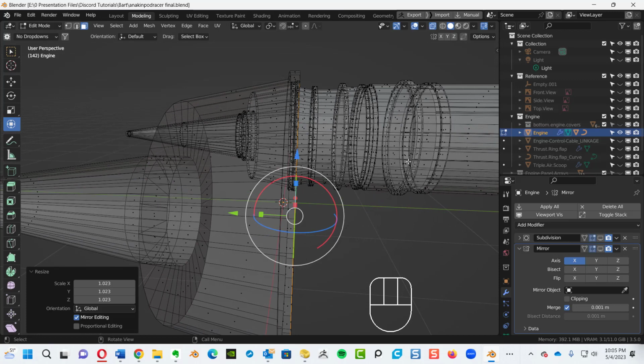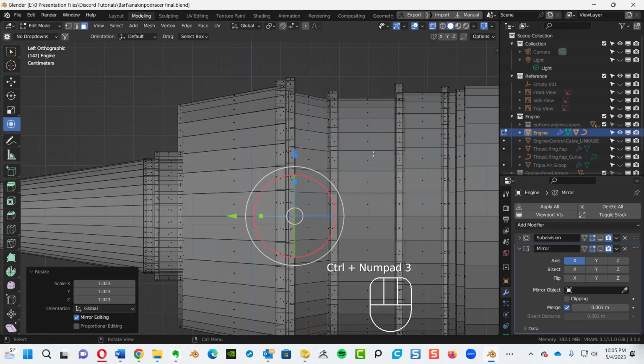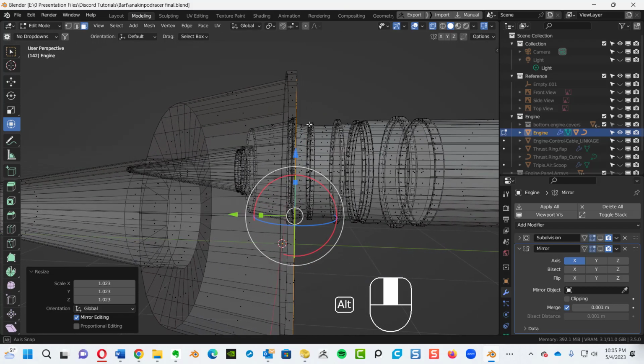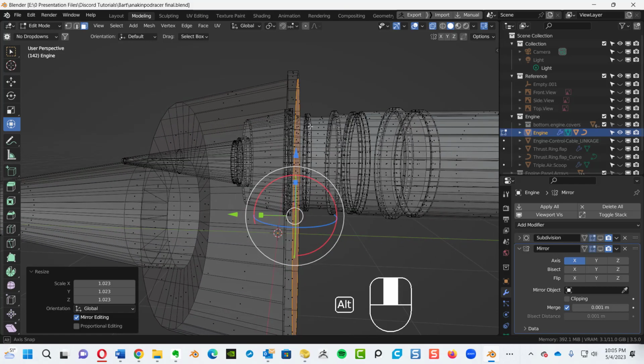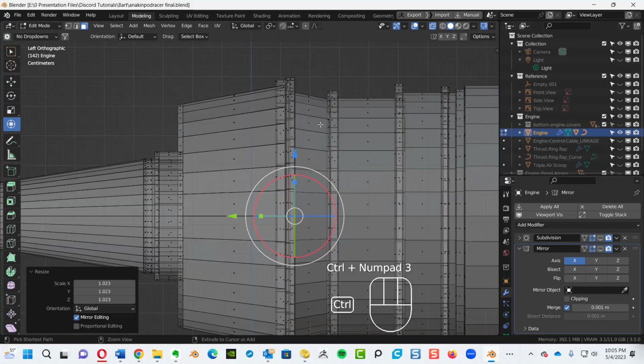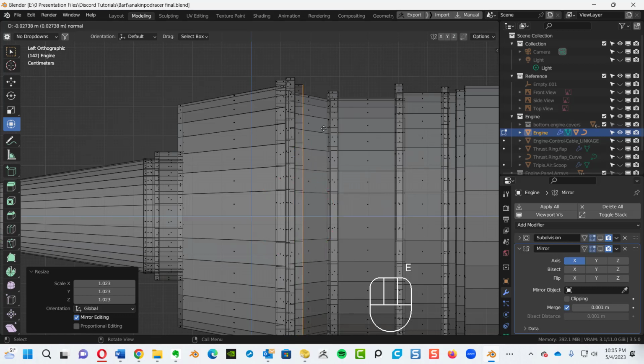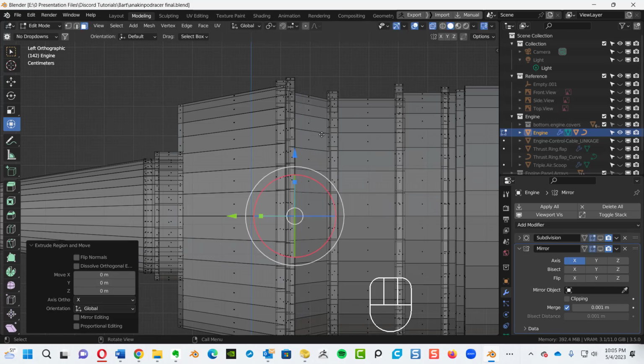Let's go back to the side view. Okay, and let me see exactly where I am there. I'm at the very end of that, and now once I brought that in, hit the E key for extrude. Now that's pretty high. If you take a look at it, I really should have extruded that in a little bit more. So I will hit the escape key,